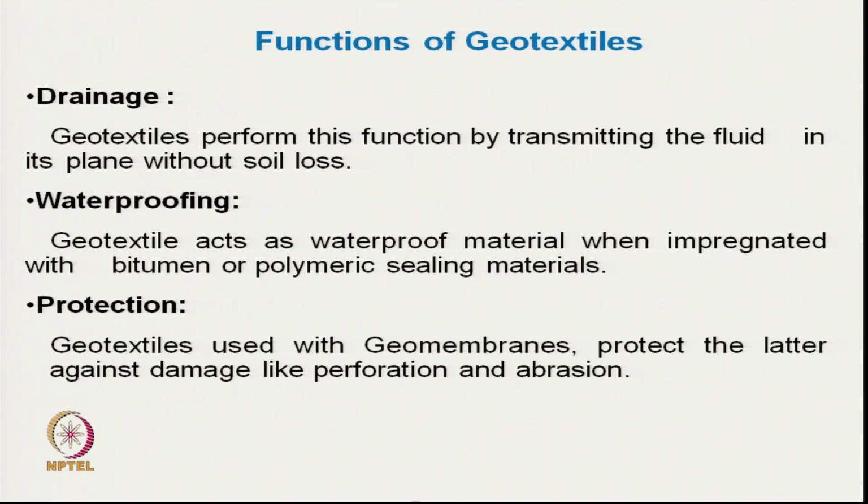It should be totally impermeable. In case of absence of geotextile, there are chances of geomembrane getting punctured. So, it will not perform its function. So, there geotextiles are used.